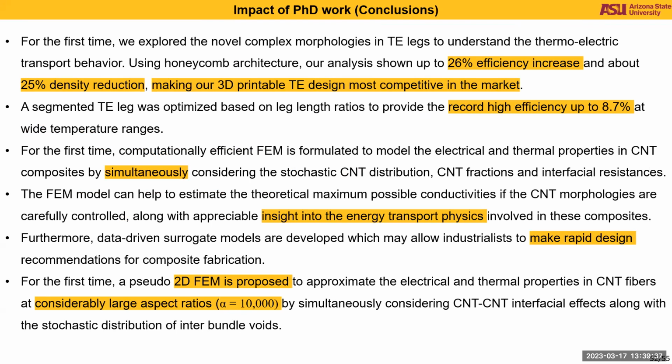For the copper CNT composite models, we developed a 2D FEM model that simultaneously considers the stochastic CNT distribution, CNT fractions, and interfacial resistances. And along with that, we developed a data-driven model that can provide rapid and accurate approximations of the transport properties through the microstructure. And finally, we developed a pseudo FEM that can basically simulate large aspect ratios of CNT fibers.